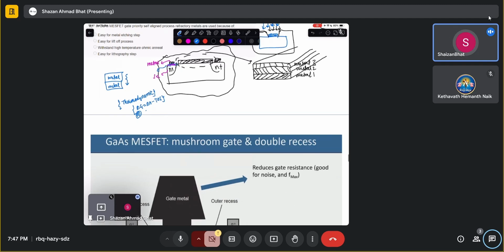What you are saying is that if you have a gate, if you deposit it over the semiconductor substrate, and you do something called annealing, that is a hot temperature, what you were saying. It's heated so that it can at least diffuse to a certain extent into the semiconductor so that it will make a good contact. But it won't be a zero resistance contact. Never. Because there are so many imperfections here: dangling bonds, surface states, defect states, traps, so much so that they are going to trap electrons. They are going to scatter electrons.